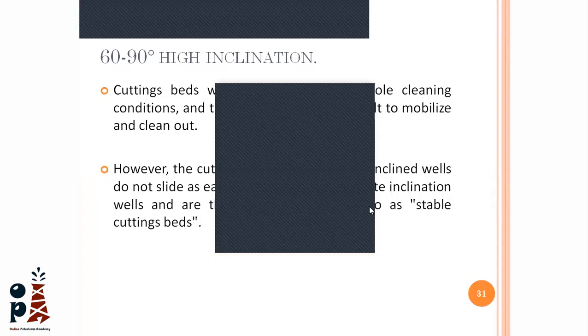Then we talked about the most important and the most critical function of drilling fluid, which is the pressure control. We talked about the mud window. We talked about the hydrostatic pressure equation and ECD for pore pressure or formation pressure, fracture pressure. We talked about the factors affecting hole cleaning. We talked about hole cleaning in different sections of the well: vertical, intermediate inclination, and horizontal inclination. So guys, that will be all, and I'm trying to catch up with your questions quickly before giving the mic to my friend Isam.